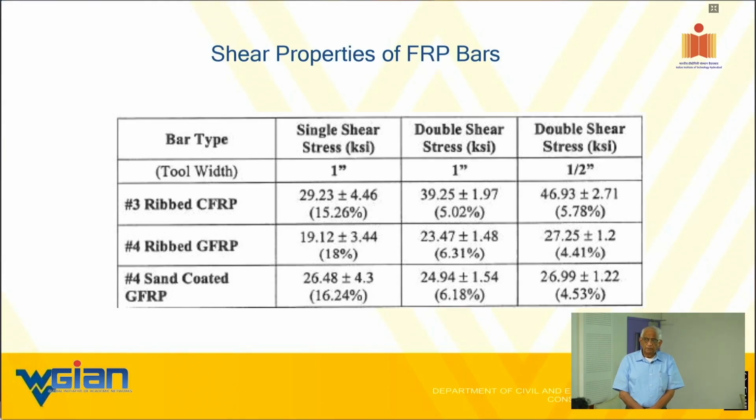So, for metals, it does not matter a whole lot in the sense that the contribution of the shear in terms of deformation is about, say, 3%, 4%, assuming you follow my rules there. That is for metals. For composite, that contribution of deformation from shear is much higher.